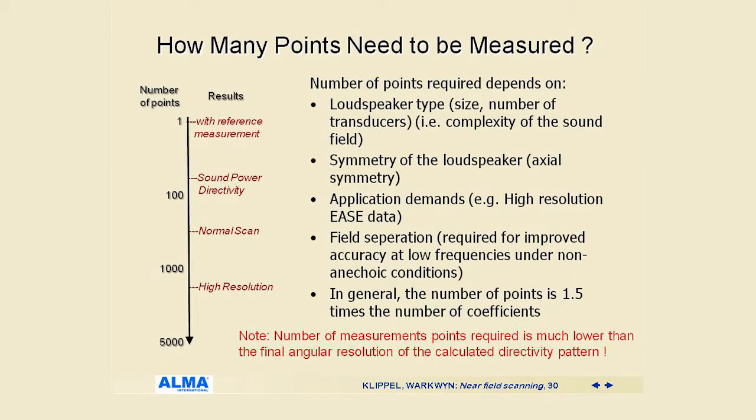How many points do we need to measure? The number of measurement points depends on the loudspeaker type, in other words, the complexity of the sound field. The symmetry of the loudspeaker is also a factor. Application demands a high resolution of the data. Field separation, is it required? Are you in a non-anechoic environment?